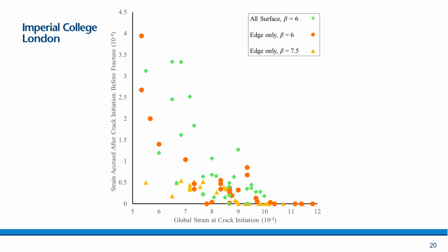So in these very broad Weibull distributions, the very low strains are very different to the higher strains, and that introduces crack arrest by having areas with very low strain failure. That's causing the initiation, but then it can't propagate through the relatively high strength bulk.